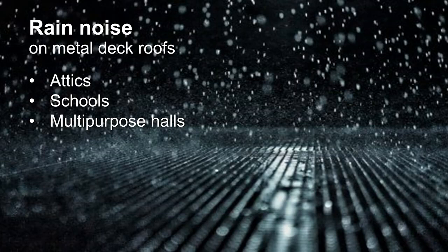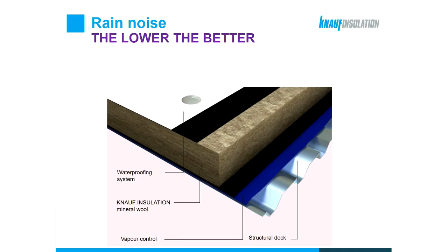And these kinds of constructions are these days very popular for schools and even multi-purpose halls. So now you can imagine it would not be easy to listen to a lecture in a classroom or to a classical music concert in a multi-purpose hall if it happens to be on a very rainy day. So rain noise is maybe not on our minds as designers quite often, but we still take it quite seriously, and actually we do perform acoustic tests to measure the impact that rain noise has.